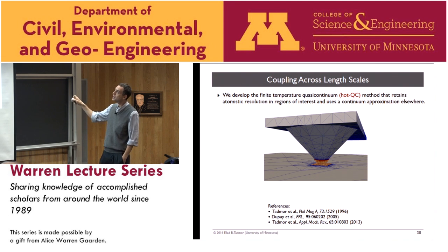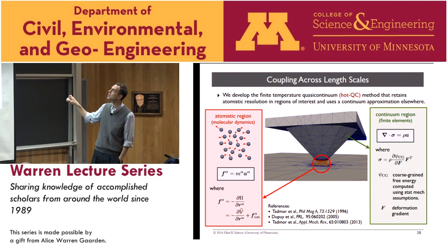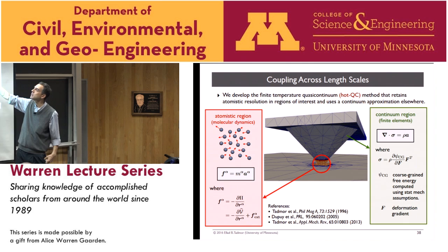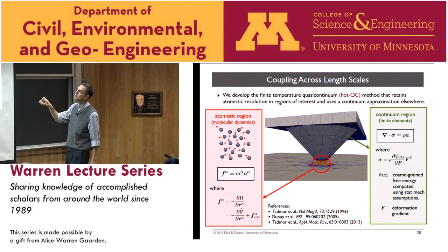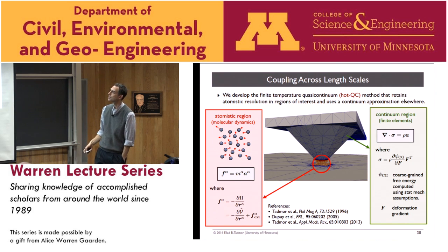And so this method allows you to do molecular dynamics in this region, where you're literally solving all the atomic interactions. And then you do a continuum model out in the far region. But the continuum is actually computed in a way that's consistent with the atomistic region. You compute the free energy density out in the continuum region, and that is computed from the same interatomic potential used in there. And so it's a consistent framework. This is the stuff that goes back to my PhD, but we've been working on it for a long time since then to extend the capabilities of this approach.